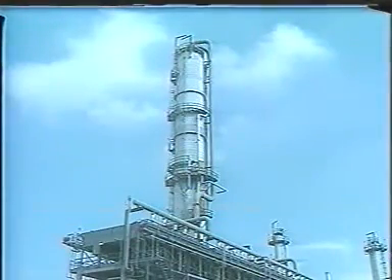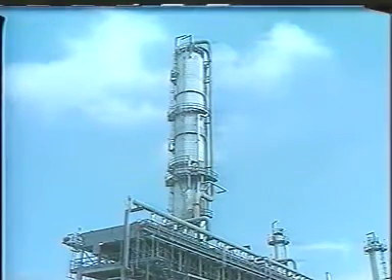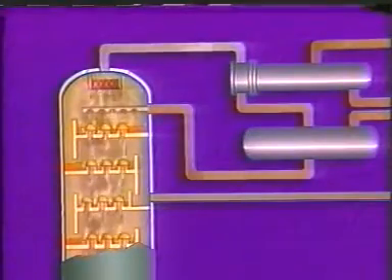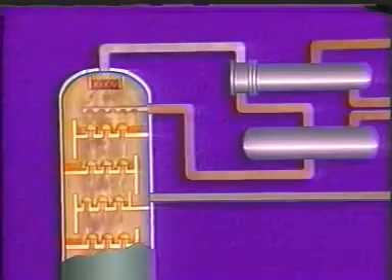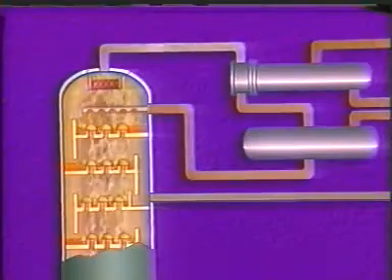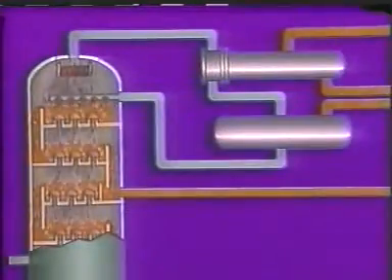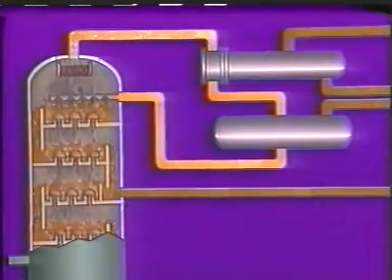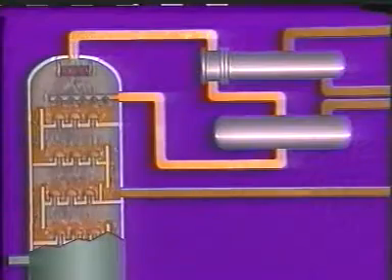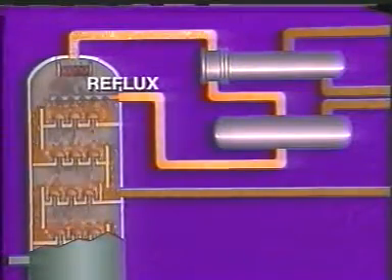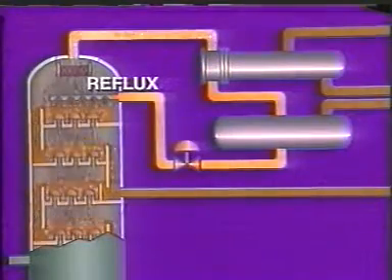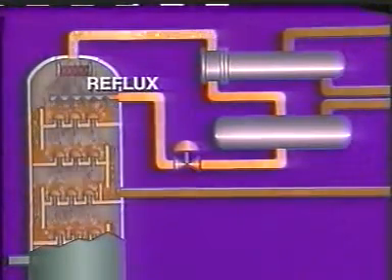This distillation tower requires specific top and bottom temperatures so the feed will divide into the desired products. If tower temperature is too hot, many heavy components will vaporize, causing the top product to be off specifications. Some of the vaporized fluid leaving the top of the tower is cooled, condensed, and circulated back to the upper tower trays. This recirculated fluid is called reflux. A valve controls the flow of reflux into the top of the tower, and this helps regulate tower temperature.